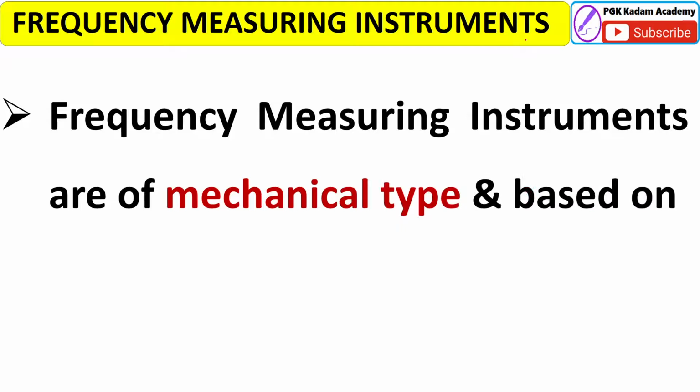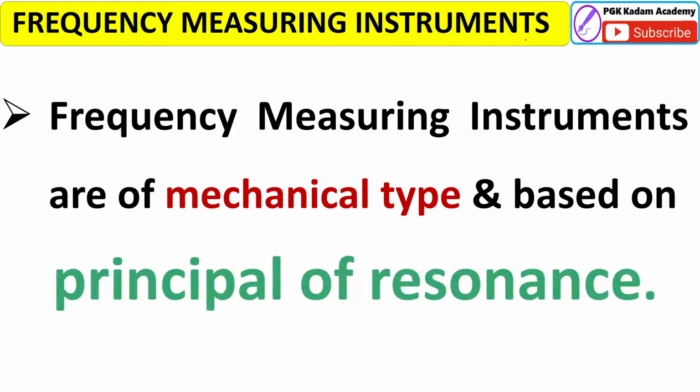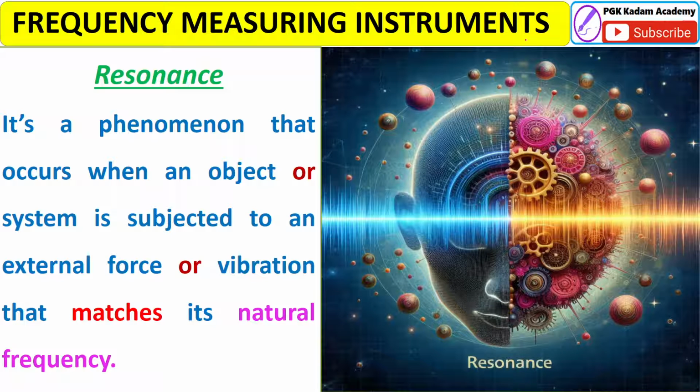Dear friends, frequency measuring instruments are of mechanical type and based on the principle of resonance. What the principle of resonance is, you already know, but for revision, it's a phenomenon that occurs when an object or system is subjected to an external force or vibration that matches its natural frequency. When the natural frequency matches the frequency of that object, then resonance occurs.